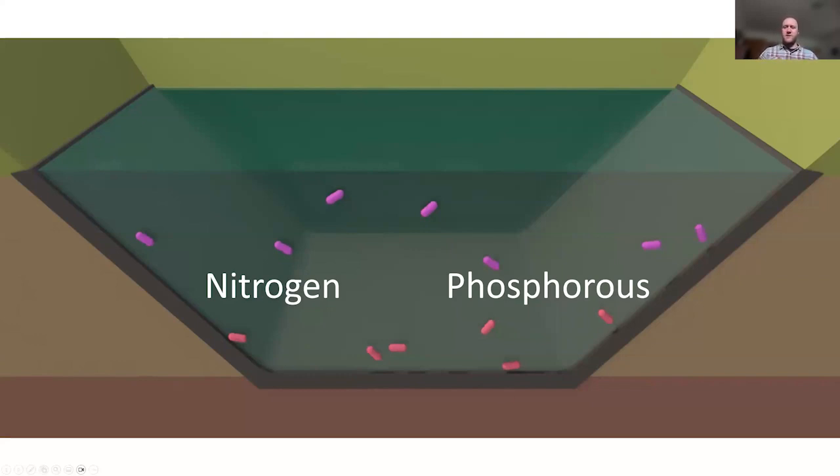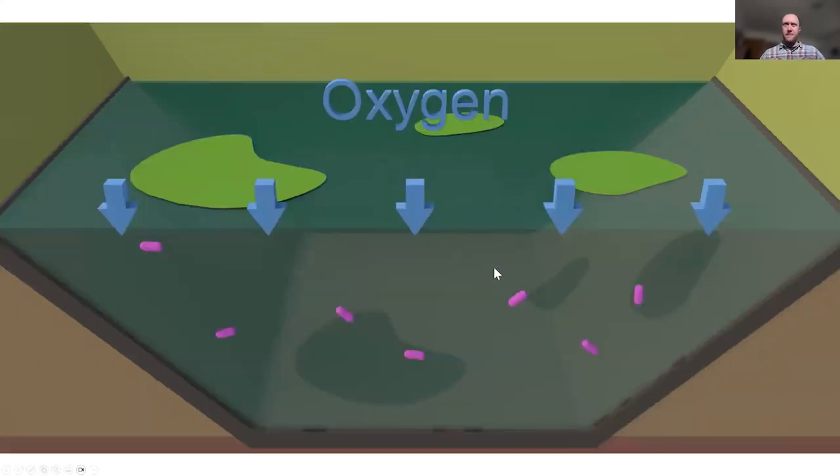And then the phosphorus, it's coming in as wastewater, but unlike nitrogen and carbon, there is no gaseous form of phosphorus. And so the phosphorus can't leave into the atmosphere like the nitrogen and the carbon can. So this phosphorus is consumed by the bacteria, and then it either precipitates out, or the phosphorus is actually in the dead bacteria cells and they settle out. So that's kind of how that process works a bit.